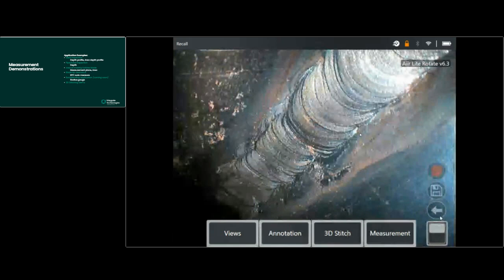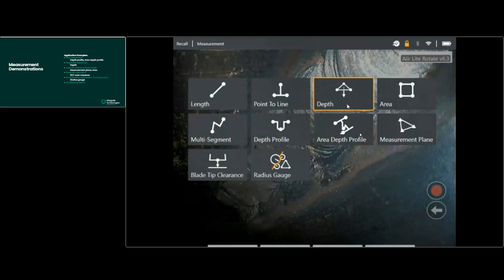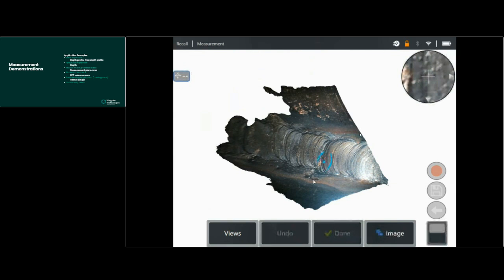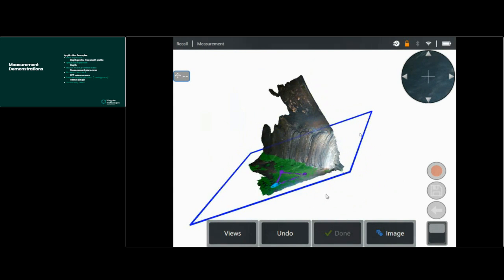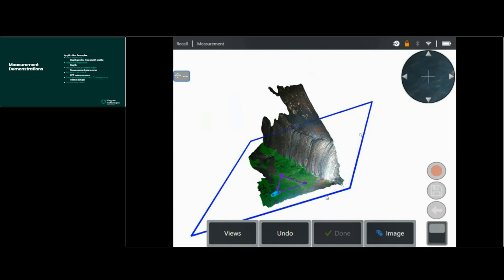Here's a case where, by using the depth function, I'd like to describe depth in this capacity as a point to surface measurement type, not necessarily just depth. What some of you might appreciate when selecting a depth measurement type is that you must determine the reference plane, by selecting 3 points.